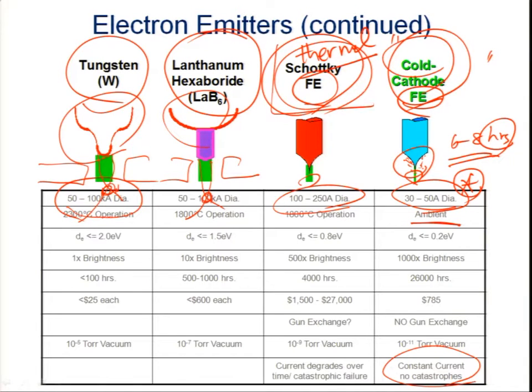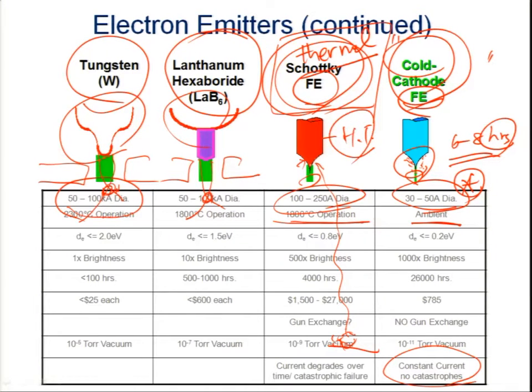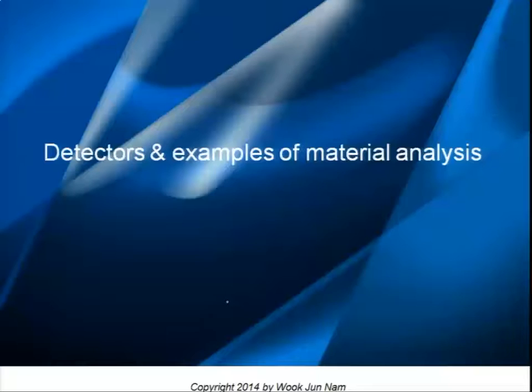But the thermal field emission source's operating temperature is pretty high. Contaminants coming out from the samples diffuse into the column and can deposit on the surface of the tip, but because of the high temperature they immediately evaporate, so it does not need the maintenance regeneration process.